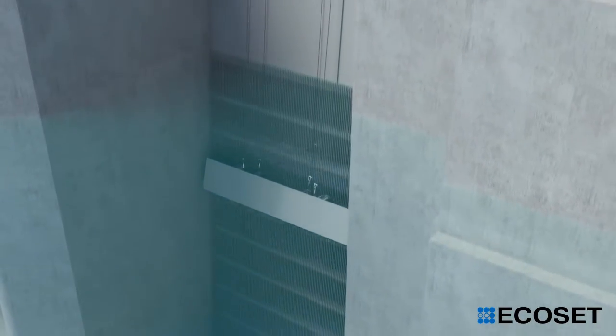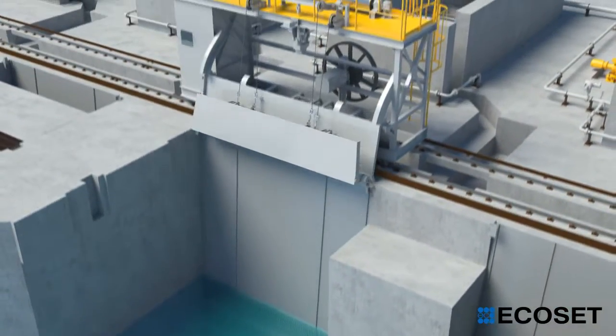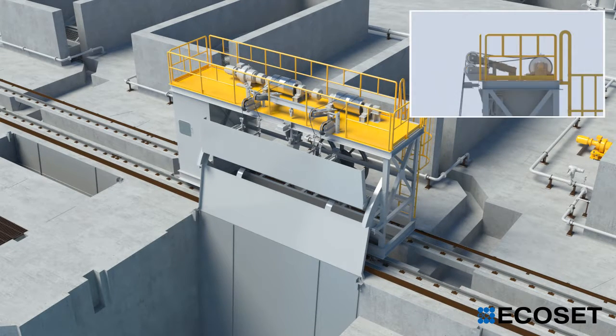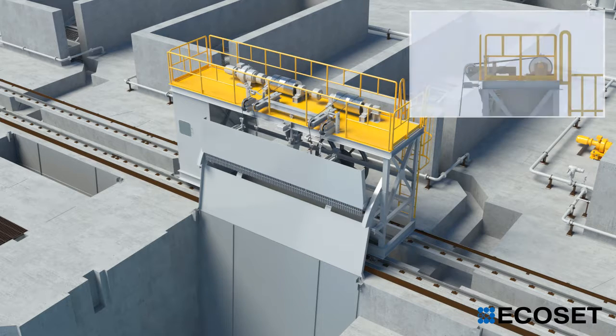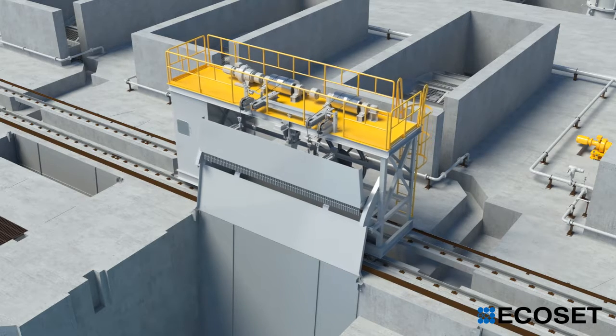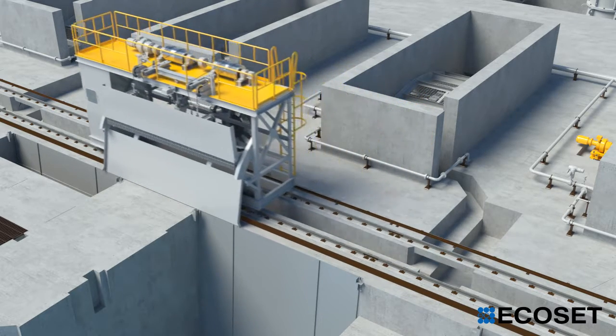Third, the rake is lifted up the upstream face of the bar screen, collecting accumulated debris. Finally, as the rake reaches the discharge position above the operating deck floor, the teeth are opened and at the same time, the debris is discharged into a concrete trough. When all the cycle operation is finished, the rake is moved to another channel and the cycle operations are repeated.